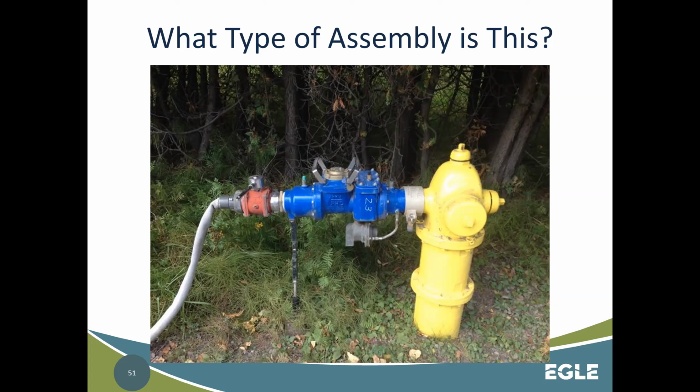There was an entire subdivision of like 500 some people that were affected and got sick with different outbreaks of fecal coliform or E. coli because there was a hydro seeding company in the neighborhood filling off the hydrant, and they had no permit, they had no RPZ, and had backfed into that entire subdivision stuff, chemicals and fecal stuff out of a hydro seeding truck. Hydro seeding stuff's not good. So if anyone's going to be filling off your hydrants, they should have an RPZ, all right? And it should be followed through the city's ordinance to be done properly.